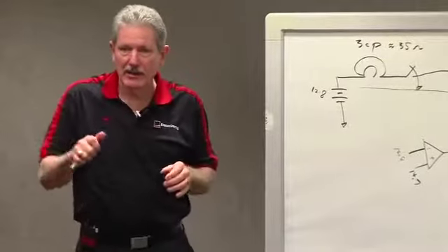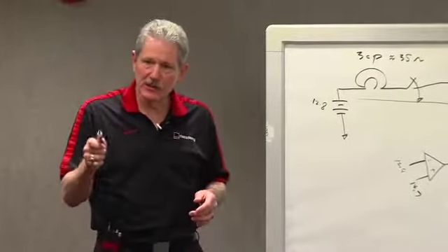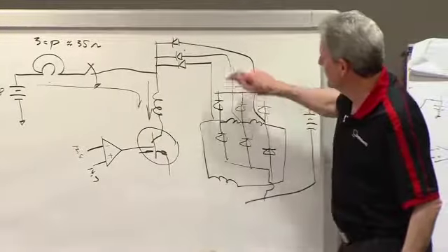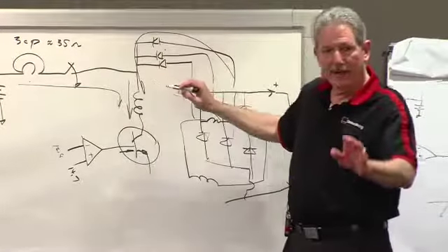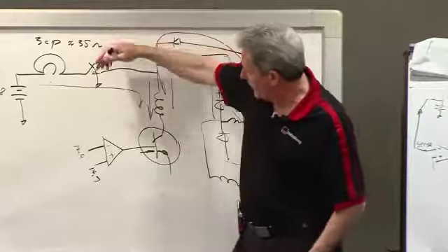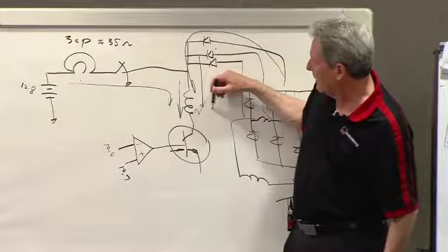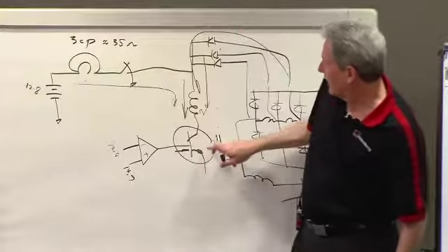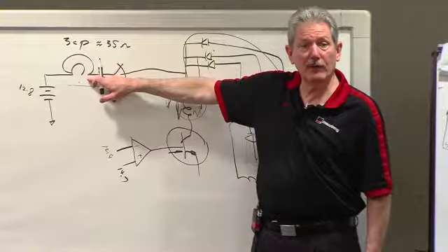Now we go into the crank condition, and the engine starts and the speed starts coming up. As soon as the speed starts coming up and it forward biases all these diodes, now current begins to flow through the trio. When that happens, this voltage comes up. Before that happens, this is let's say a 2 ohm field. So I've got 35 ohms and I've got 2 ohms, so I've got about 37 ohms. So the light is going to turn on. I got about a volt here and virtually nothing here. So the light turns on with full brilliance.